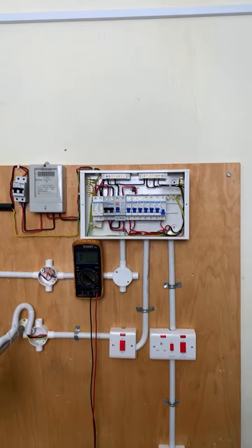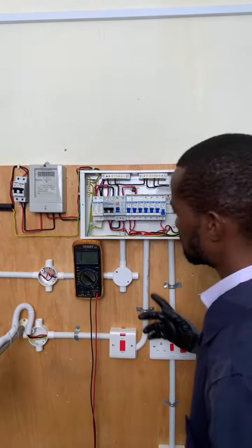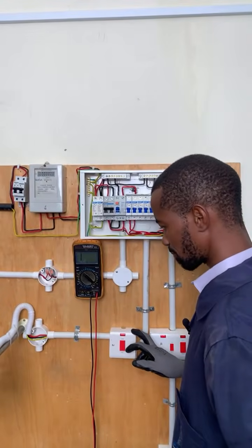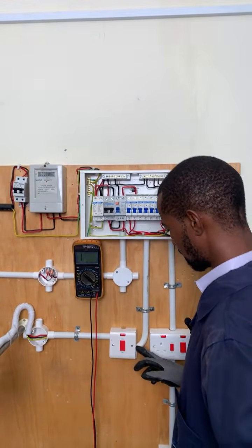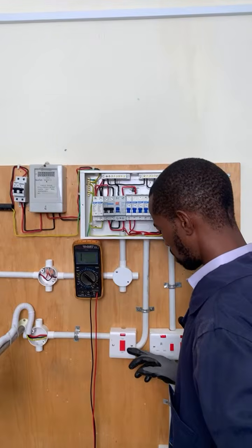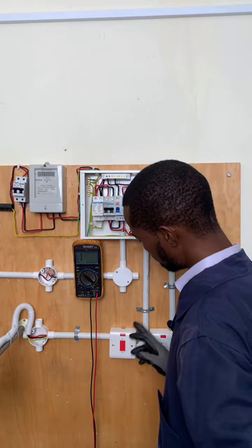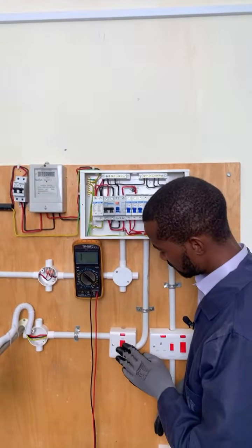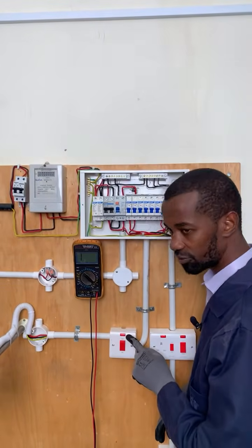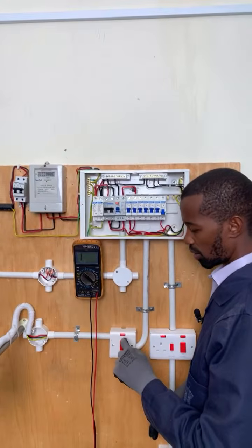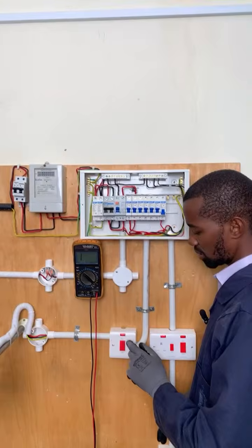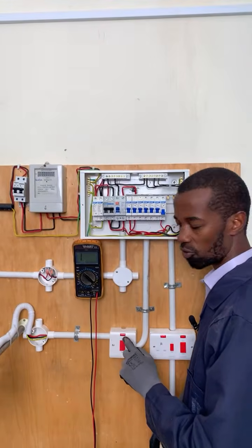Right. So something else that I would like to elaborate when it comes to troubleshooting is definitely on the wrong fixtures. Fixtures sometimes fail. Let's say it is this switch here. If it is not supplying power to this instant shower head, then the switch itself is faulty.